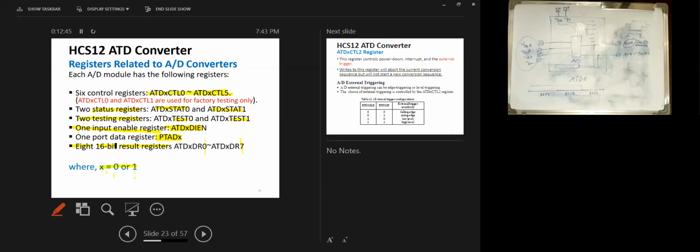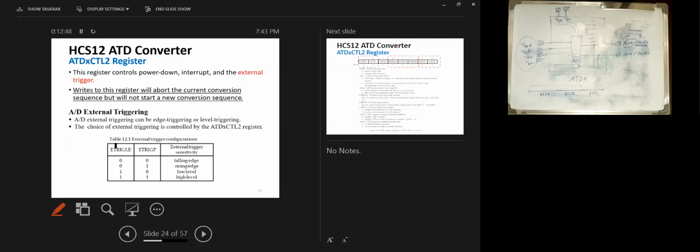All right, so next time we'll look at these registers, how to use them to configure and use the A to D. But in order to save some time, please help me by going through these registers. They are very simple. If we understood the idea that we have an A to D with the channels and a clock, we can pick the channel to take the sample from and convert. And our pick can be from multiple channels, over rounds or over sequences and all that stuff.